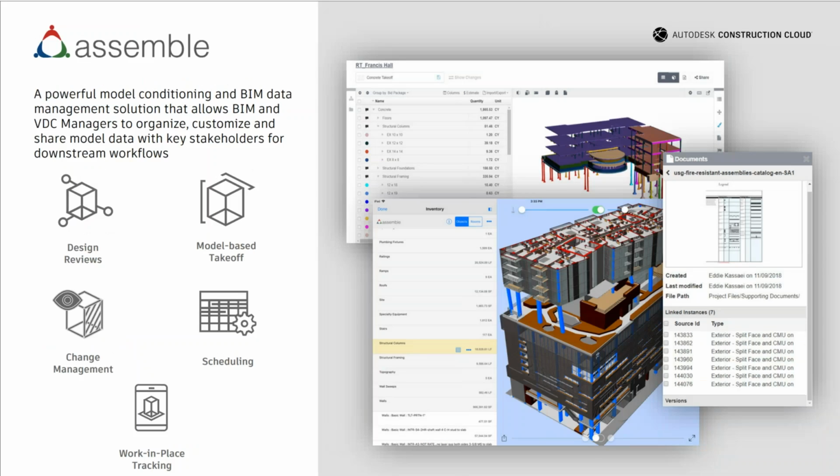So once a design is at a certain point and the model is ready to start with the cost estimation, that's where we're doing the quantification that then leads into the other third-party apps that you actually use for cost estimation. This is about getting all the data ready for that. So you can link the models directly from BIM Collaborate into Assemble, and then you start breaking that model up in ways that Revit doesn't natively break the model up, and put it into groupings of how different aspects would be quantified for filling out cost management later.